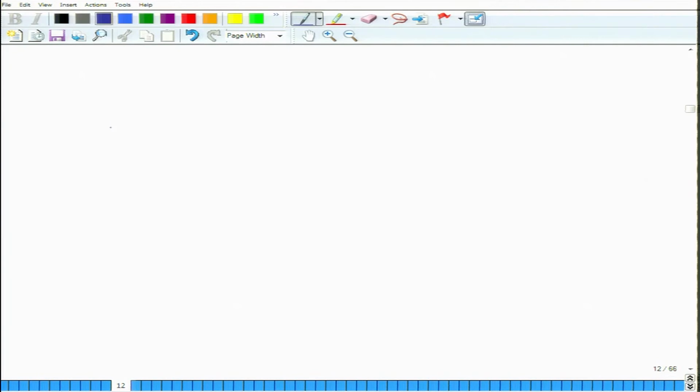So, I will again draw a unit cell. One thing that I forgot to mention is that the representation HKL is independent of the crystal system. Now, multiplicity may change, but how you determine a plane, how you draw a plane, is independent of the crystal system. So, that applies to all the crystal systems. As long as you have a 3D unit cell, you draw a plane in identical fashion, irrespective of the type of the crystal system. Okay.